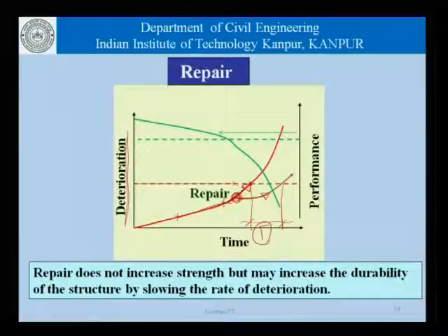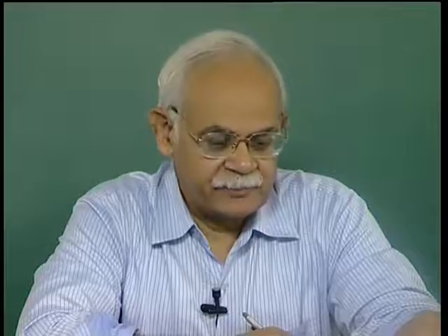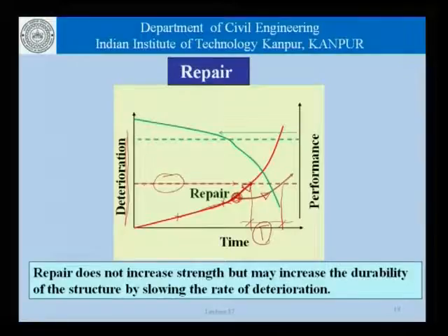An engineering framework would mean that depending upon the structure that we are talking about, whether it is a marine structure, whether it is a structure in the cold climate, we define appropriate deterioration parameters and we try to follow those parameters. We measure them periodically and find out how they are changing. Not only that, we also need to find out what is the maximum acceptable level of that particular parameter. That will call for corrective action, or before that value is reached, the structure should be repaired.